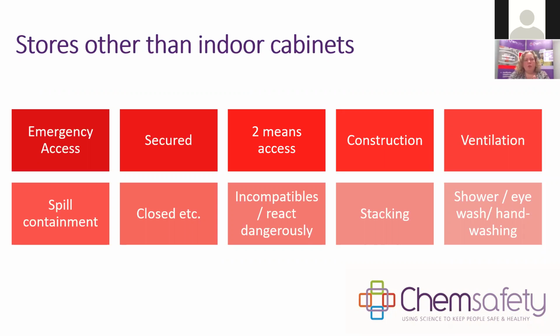So a store or a place where you're keeping your substances that's not an indoor cabinet needs to have access for emergency services. So it should be located on the ground floor unless you've got approval from WorkSafe. The store needs to be secured. So aside from our requirement earlier for securing substances, the store needs to be secured so that only authorised people have access. And if it's a larger store, more than 25 square metres, then it needs to have 2 means of access. It needs to be constructed, if it's a new construction, of non-combustible materials and that are resistant to attack by the substances being stored.